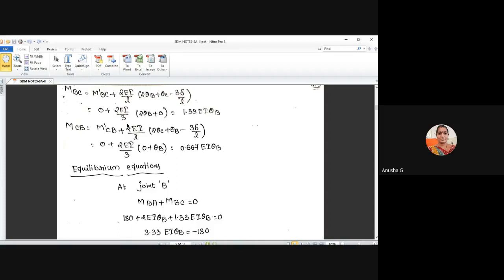In last class the span for AB, how much, ma? 6 there. Here the span is 3. Okay. Then you will get the other equations. There are the 4 equations you will get here. This is step 2. In step 2, you have to calculate the slope deflection equation.